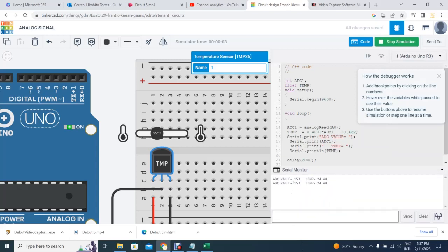As you can see, it's telling me the ADC value equivalent to 24.44, which is basically the 25 degrees plus or minus 0.5 degrees, which is basically the error of the measurement, but it looked good. Now let's go here to minus 40. The minus 40 is giving minus 40.64, not bad, pretty much right within plus or minus 1 degree or less than that.